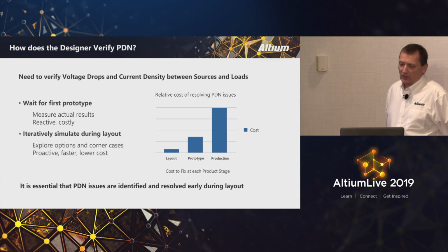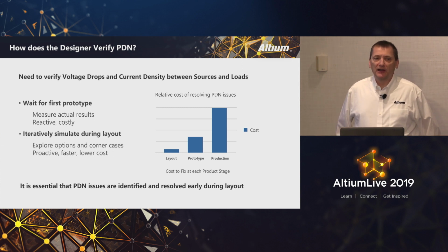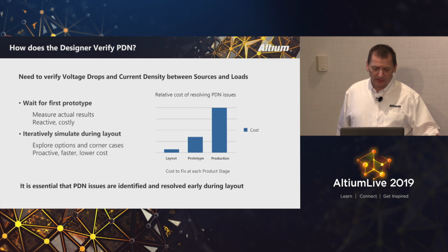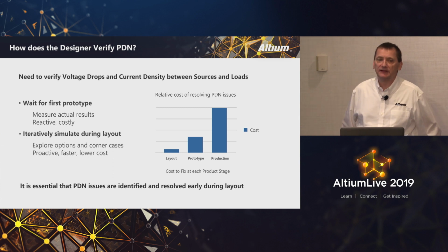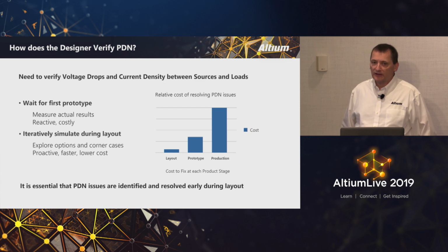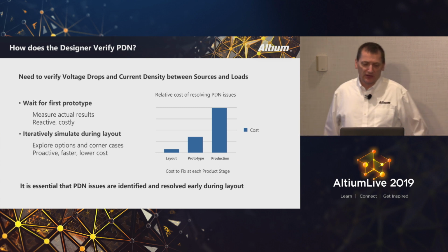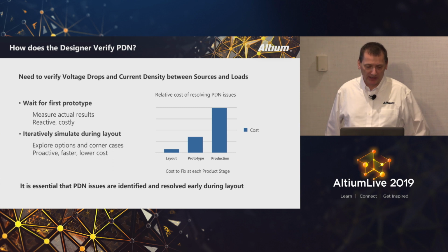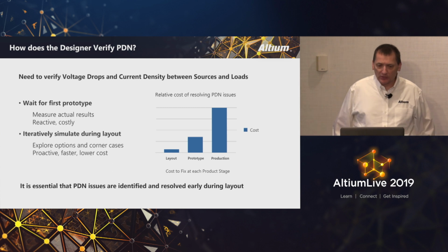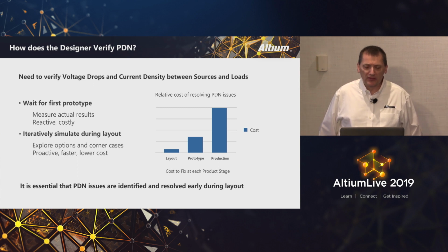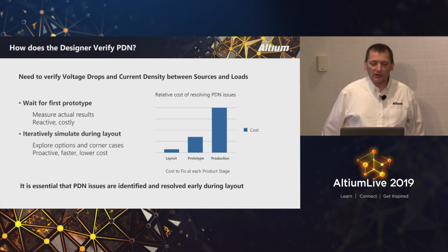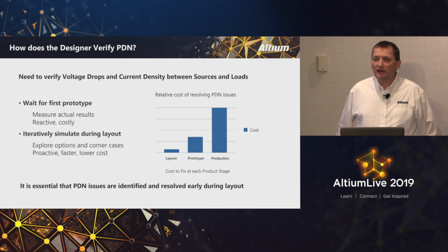So you can vary your analysis by creating different tests, and therefore you can come up with high temperature tests, or different corner cases, different temperature, different worst case loads and whatnot. So you can play around with the variables and then be sure that what you have will likely do well when fabricated. So, generally it's probably a combination of both. Thoroughly analyzing the prototype, but also making sure right out of the gate, just doing a little bit of math and verifying what you have can go a long way and save you some problems.